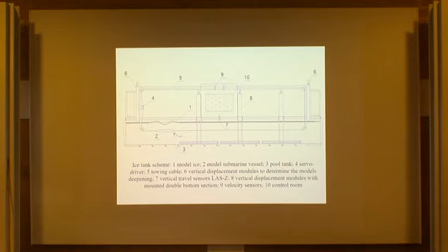The simulation scale was selected equal to the size of the ice tank, with the length of the channel providing access to the steady motion of the model submarine vessels. The width was sufficient to eliminate the influence of the waves reflected from the channel sides on the principal wave systems.